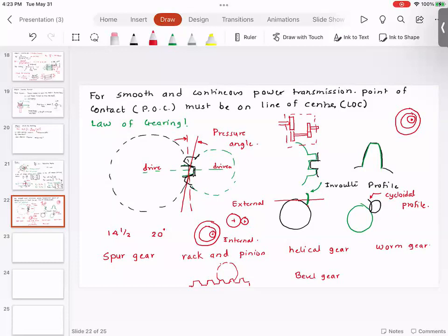And if you look at the rear differential, you usually have a bevel gear, wherein you have a gear like this. You have the gear that comes from the prop shaft, and you have the gear like this that goes to the wheel. So this is the prop shaft. And if you see, there is this pumpkin in the rear differential. If you look at the center lines of the shafts, they are at 90 degrees.